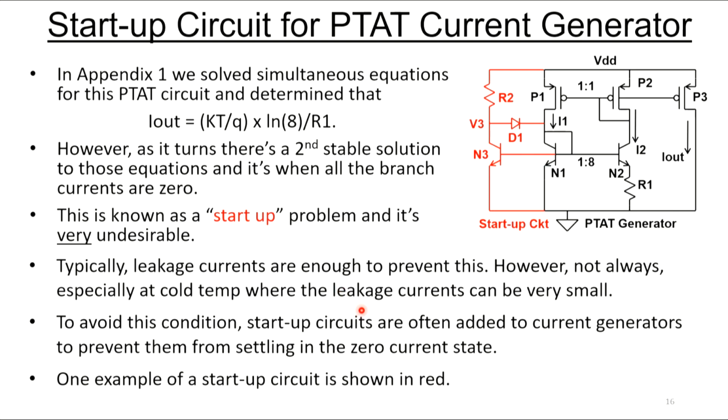Typically, just the leakage current is enough to kick these things on. All you need is a little bit of current to trickle through, and it'll kick it on, and it won't settle at the 0 current state. It'll settle at the other stable point that you want it to settle at. However, not always, and especially at cold temperature. The leakage currents can be very small at cold temperature. So these startup problems, you'll never get a startup problem at hot. It always happens in cold temperature.